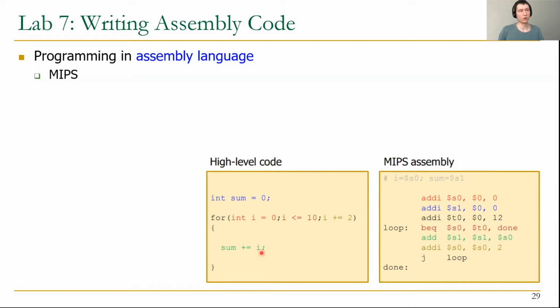You can see that each line represents a different instruction, and each instruction has its own operation. So this add immediate represents what kind of operation this is, and also other operands as source and destination operands, right? So what two numbers should add together and where to write the addition result.